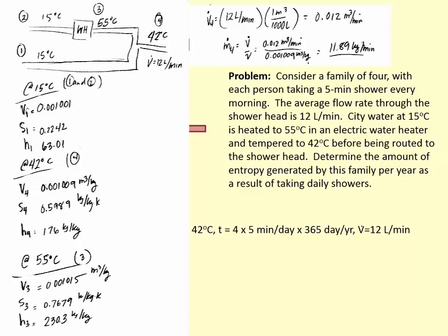Okay, so now there are a couple of different systems we can look at to find mass flow rates, right? So we have m dot 1, m dot 2, m dot 3, and m dot 4. We can perform an energy balance on that part, which will give us m dot 1, 3, and 4 in an equation. Then we can perform a mass balance on that same part, so we'll have 2 equations, 2 unknowns. We'll be able to go from there.